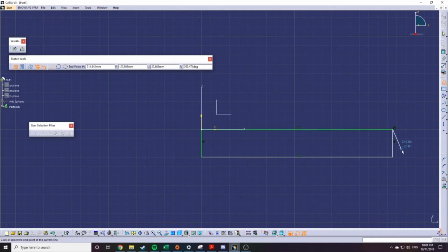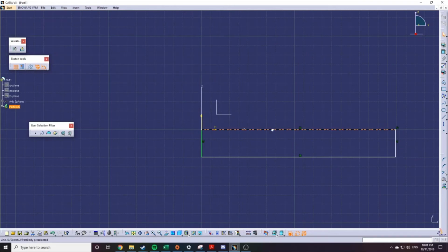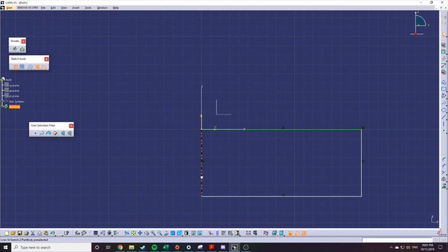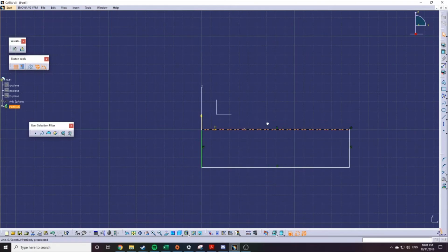So we're just going to draw a very simple box to begin with. Now, you can see these 2 green lines and there's 2 white lines. So these green lines, I cannot change the height that they're at, and I cannot change the starting position. So I can change the length of the line, but I can't actually change the location of the line. It's just a continuation of the line that I extend or contract. As for these ones, I can definitely change the height and the length. So nothing's constraining them too much. There's no position that they're holding to.